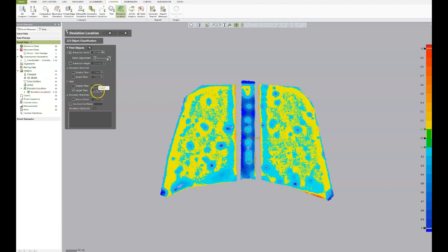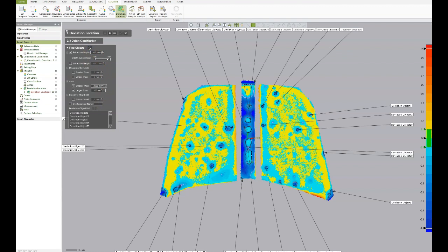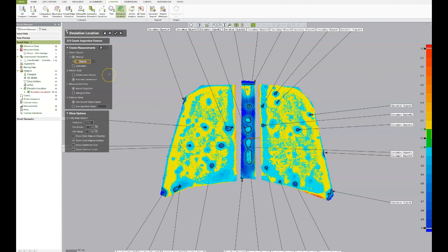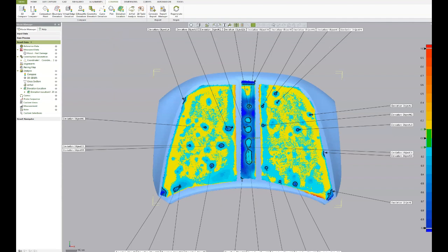So like I said, we're going to use area. We want anything that's larger than, let's say, 100 square millimeters. We're going to cap that out at 2,000 because it'll eliminate some of the areas that it'll detect along the edges of our selected regions. And now you can see it identifies all the areas that fit the parameters of what we just said. From here, we have our mesh itself, and we're ready to run this on our report.